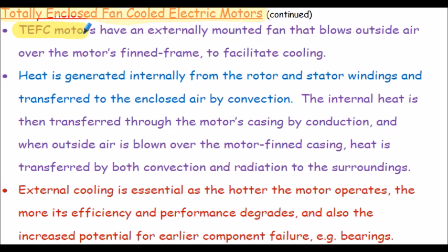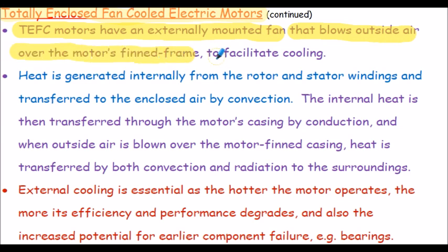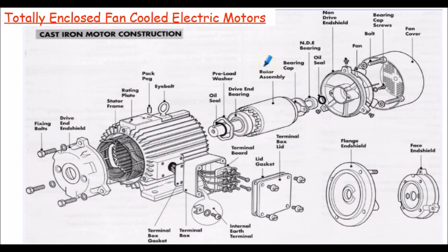TEFC motors have an externally mounted fan that blows outside air over the motor's finned frame to facilitate cooling. Here's an exploded view of a totally enclosed fan-cooled motor. This is sometimes termed the stator frame, shown here, and you can see the finned casing shown here in the diagram. Just note for reference that the fin construction is used to generate a larger surface area and thus allow for greater heat dissipation and thus greater cooling of the motor.